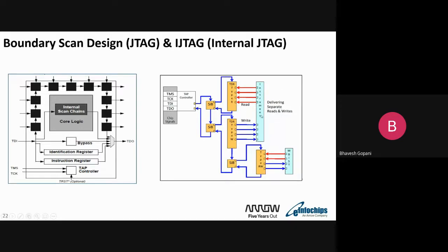Once the PLL has generated the frequency, we can also verify those things through simulation, because in simulation we are applying the same vectors on the chip, on the DUT we can say, and we are measuring the output: whether PLL lock is happening or not, what frequency is coming, whether only 1 gigahertz is coming, or 990 or 900 is coming. Those things we can do, and we can also check whether all the internal values, like reset, are coming fine or not. If reset is not coming, then our PLL will not behave as expected.